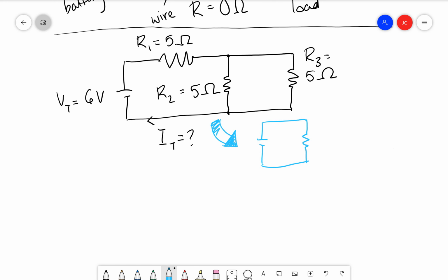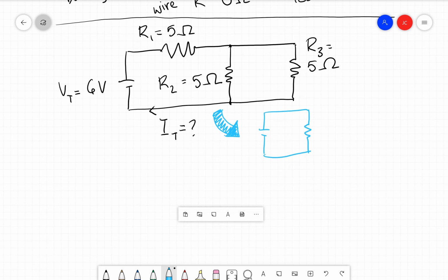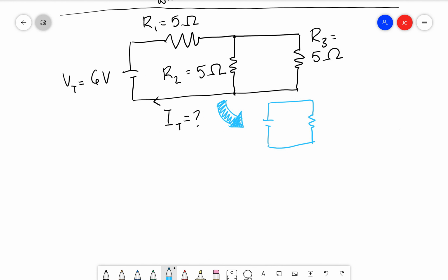And in order to do this is a little bit of work, but not too much. So let's just take a look. The first thing we're going to do is tackle these two resistors here. These two resistors, isolated on their own, ignoring everything else, are a parallel circuit. You can tell. There's two paths, goes one path, two paths, has a junction. It's a parallel circuit. We are just going to take those two resistors and combine them, smush them together.